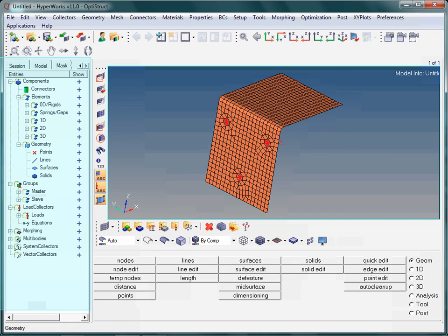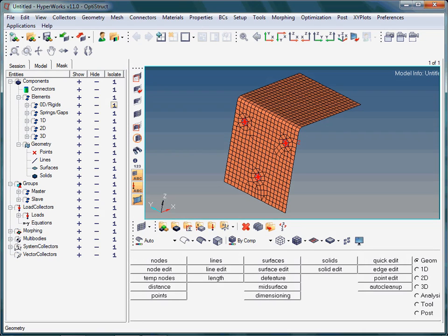In order to change the size of a tab area or browser window, click on the vertical edge and drag it to the right. By default, the tab area is located on the left side. You can also place the tab area on the right, or even allow tab areas on the left and right side of the window, hence allowing you to customize the look and feel of HyperMesh.